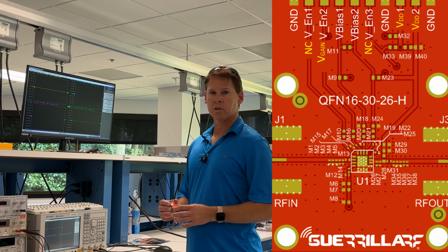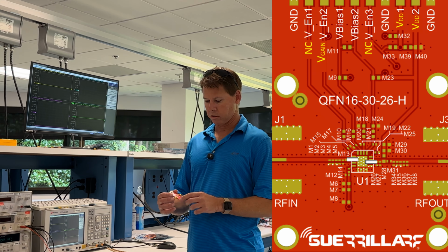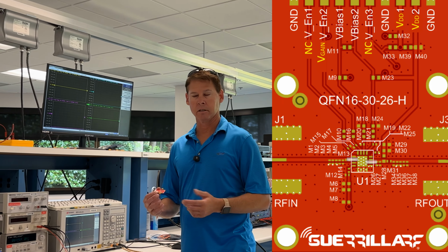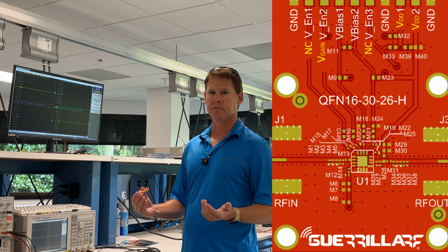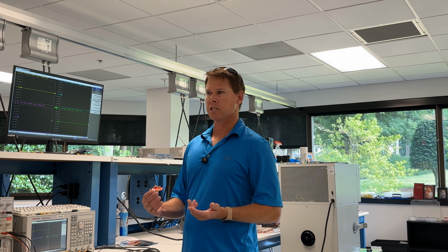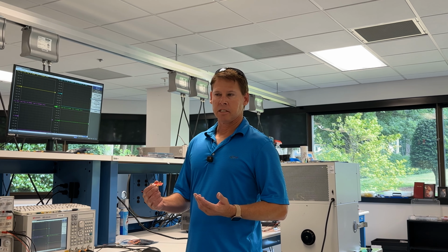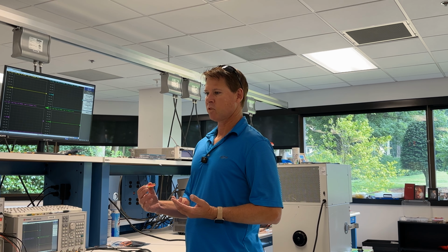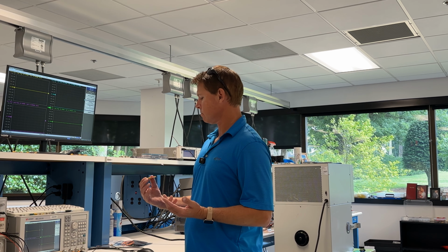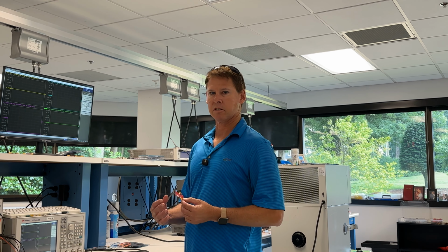And you can measure short, where we actually put 0 ohm shorts to the ground slug. It's another method of getting the extension, and the analyzer calculates all the delays that it would take to get those extensions.